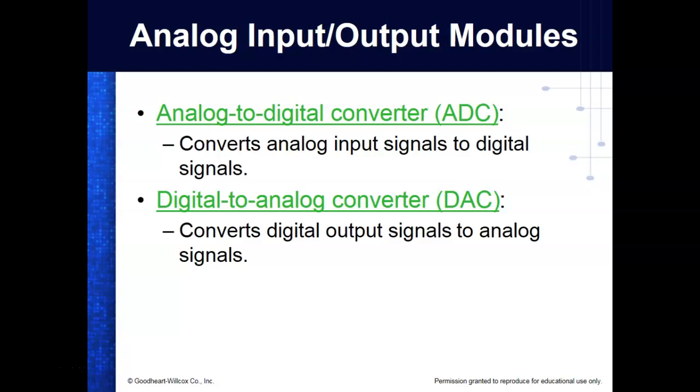So if you got a PLC that has an analog input, what does it do? Inside it's got a special thing called an analog to digital converter, which basically converts an analog signal into a binary number. So these PLCs have two analog inputs. They allow inputs from 0 to 10 volts. It can be anywhere between that. And it's got a 10-bit A to D converter, so it's going to take that and split it into 1,024 different binary numbers.